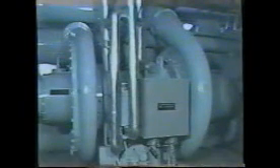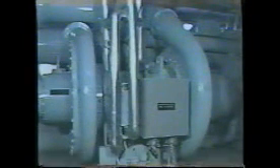This is a two-stage centrifugal compressor. In a compressor like this, with more than one impeller, the discharge vapor from one impeller enters the suction intake of the next one. Let's follow the flow path of the refrigerant vapor through this centrifugal compressor to see how a two-stage compressor can increase the vapor pressure. As the vapor moves through the first impeller, its pressure increases by a certain amount. As it passes through the second impeller, or the second stage of compression, the pressure increases further. This results in a highly compressed vapor leaving the compressor.